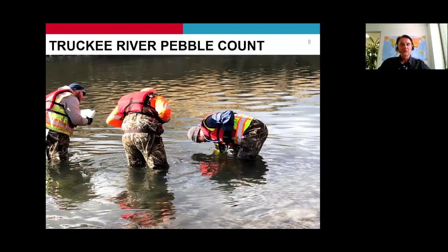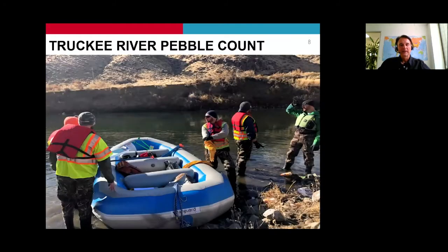This is our crew of the geotechnical subconsultant CME. They were conducting underwater pebble counts at 54 locations in November 2019, which was quite a heroic effort in 50-degree Fahrenheit cold water. At each location, they collected the surface and subsurface samples. Overall, 108 samples, which took about 5 weeks due to unfavorable hydrologic conditions in the river.